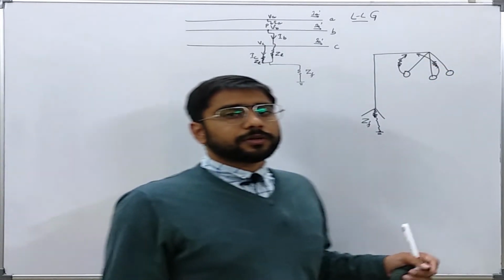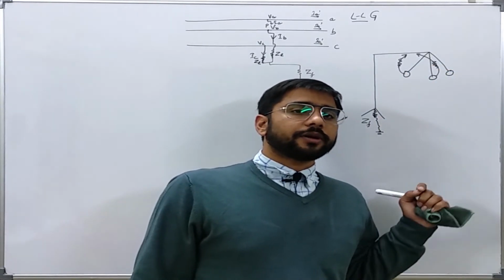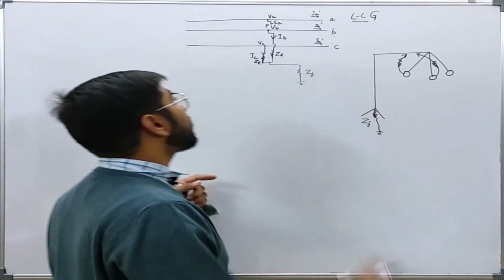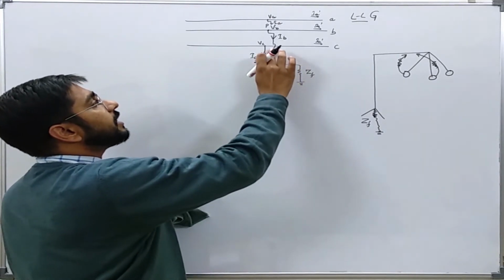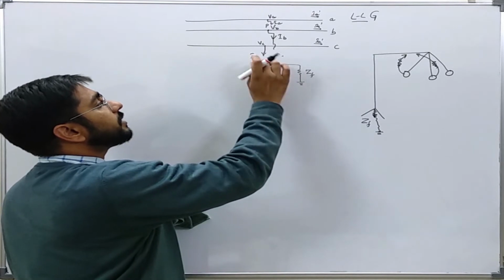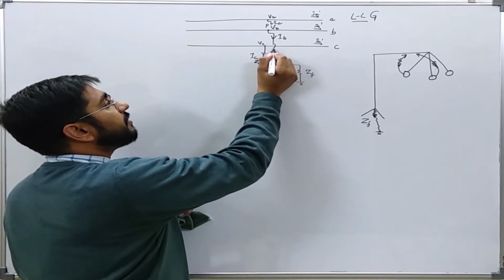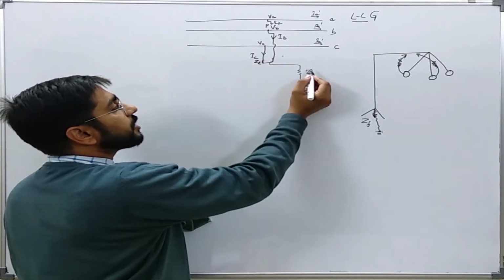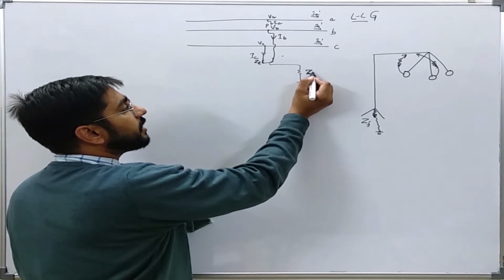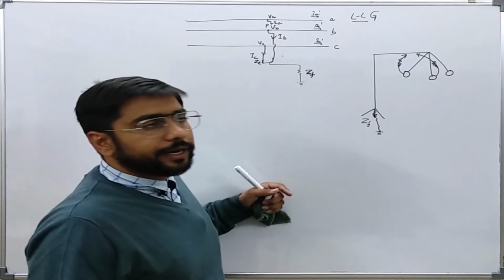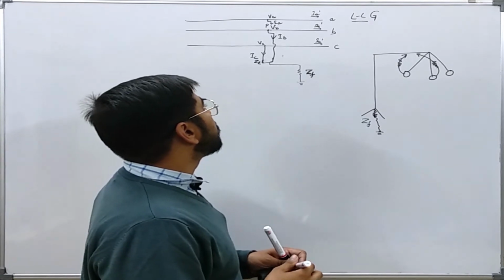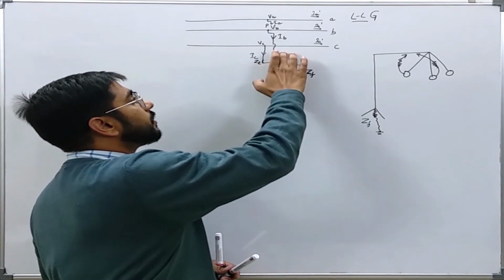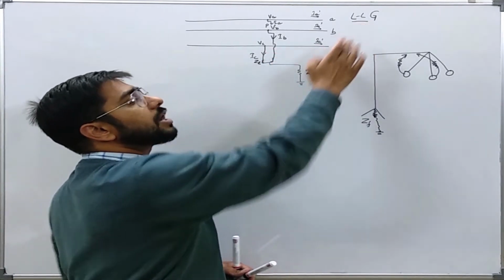So to reduce the complexity of our analysis, we assume that this ZL is negligible and that this is a direct short circuit between the phases, and we just assume this impedance in the earth circuit. Okay, so this is the equivalent scenario for double line to ground fault.